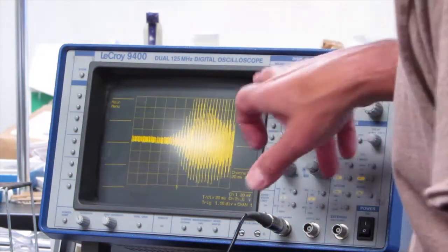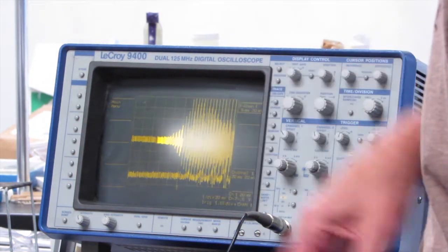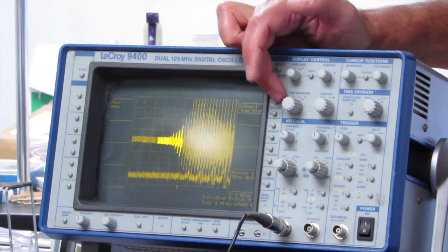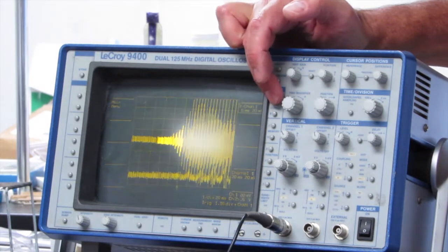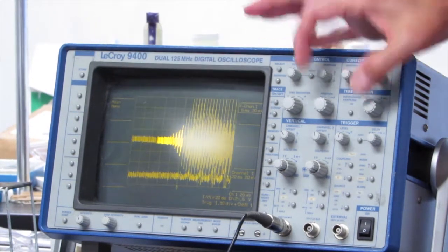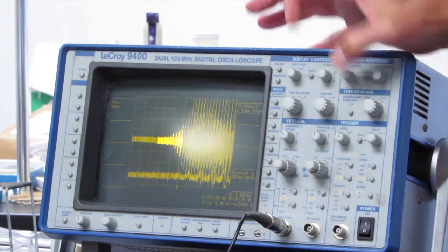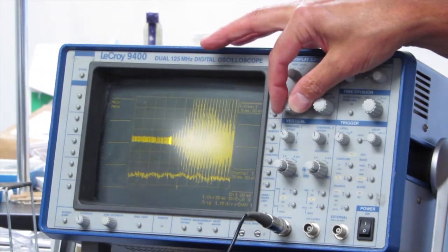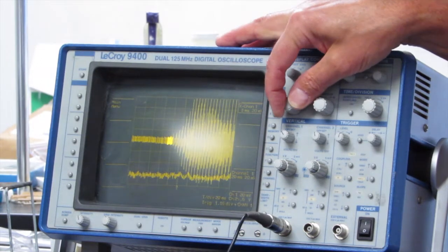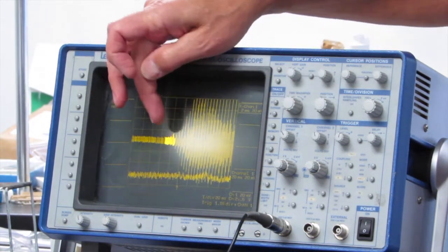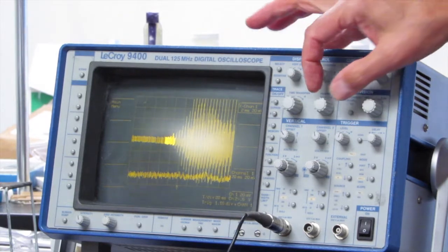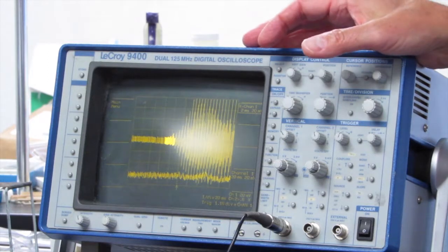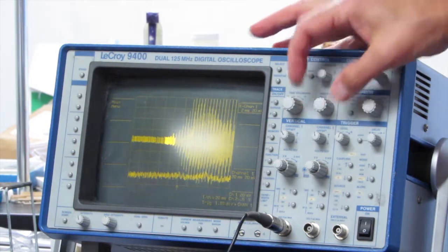And now I can do something cool here with the digital scope. If I want to get in and look at this, I can expand on A, and if I press that function, it gives me a second horizontal sweep, a time magnifier, and by turning that to the right to higher and higher speeds, it will sweep across just one section of the display. It'll amplify it? Amplifies the time. Or sorry, makes it bigger. Stretch it out. Yes.